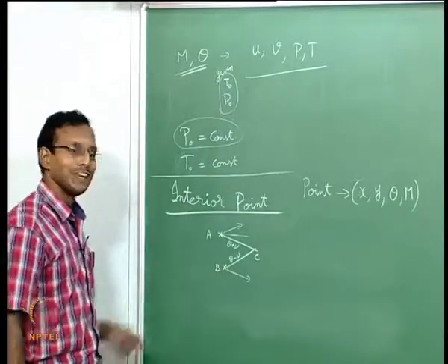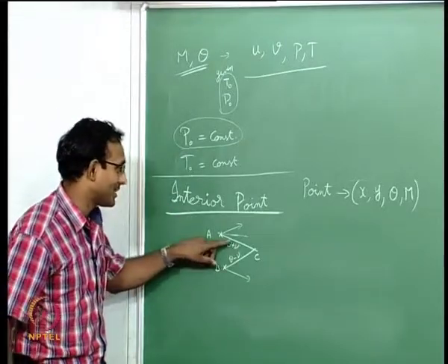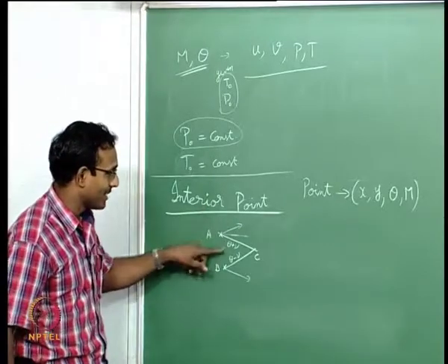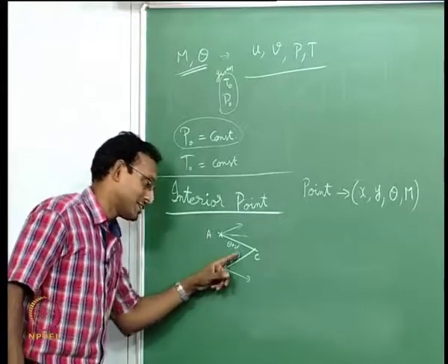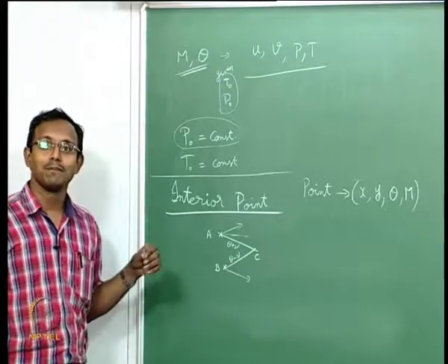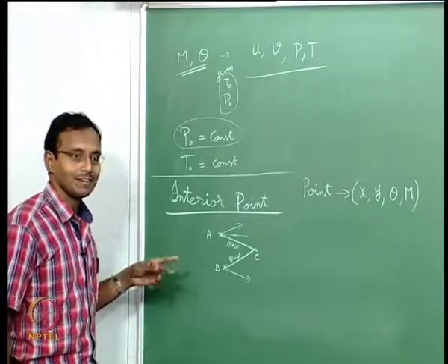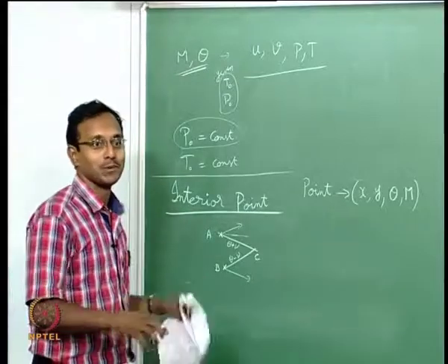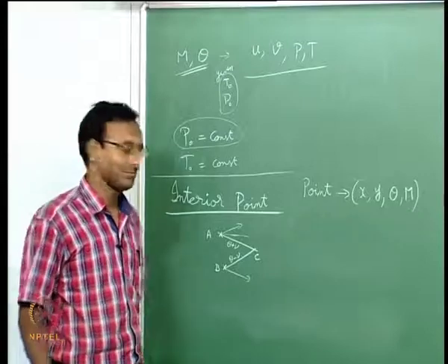I like to think about it as positive and negative. It makes sense when I want to use the opposite sign in theta plus nu versus theta minus nu. If it is a negative characteristic, it will have theta plus nu constant. If it is a positive characteristic, it will have theta minus nu constant. That is why I prefer positive and negative. But it will get confusing after some time, as angles are not going to remain positive or negative. There it will help to have left running versus right running.